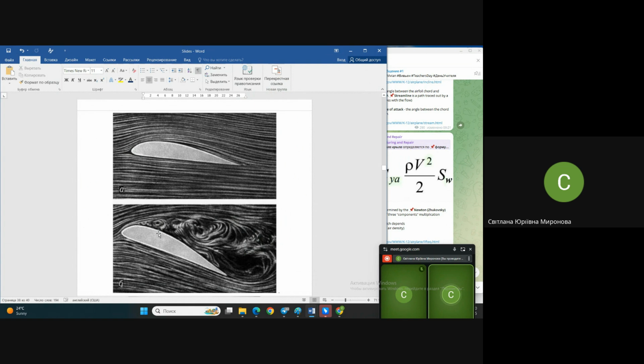Quite clear that in this case, even if it's not a stall yet, if it's just turbulization of the boundary layer, it's already not good, let's say, because you get an increase in drag. Increase in drag means that you are spending more fuel to provide the same motion forward. You will be forced to increase thrust and fuel consumption, because to provide the same motion, you need more thrust, and more thrust because you have greater drag somewhere, either on the wing or somewhere else.